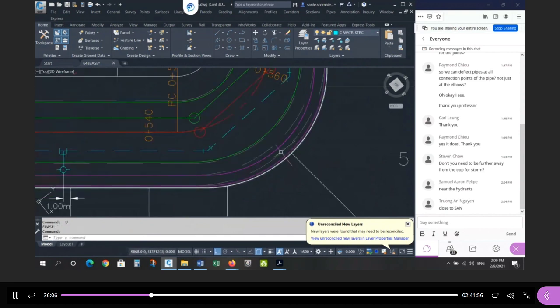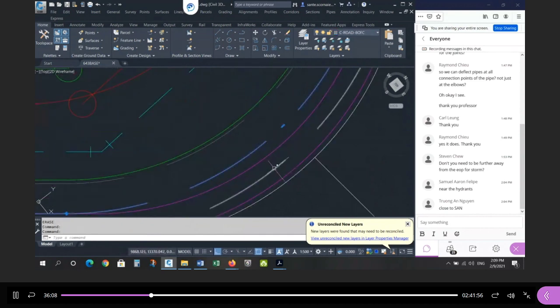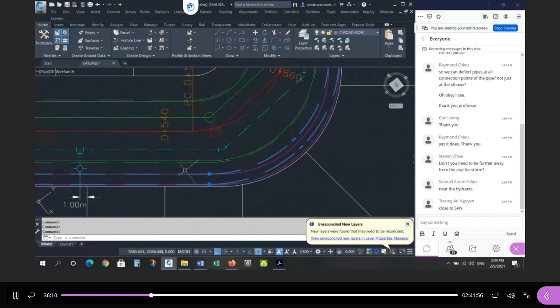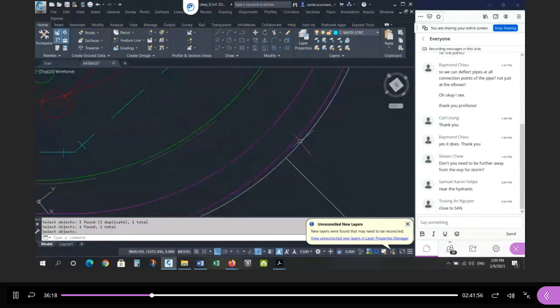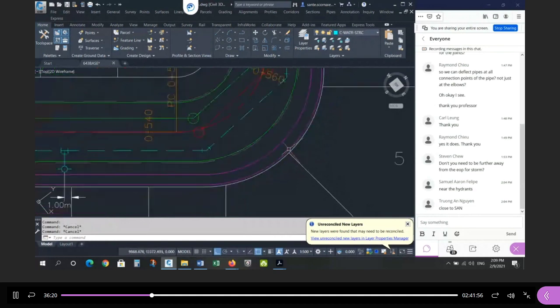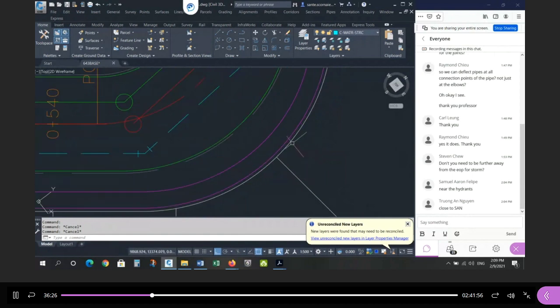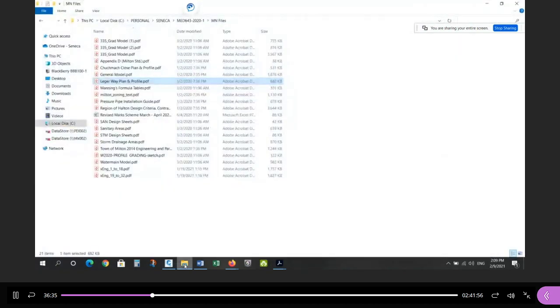Either way, either solution, you could put the sidewalk here and have a constant boulevard width, right? Back of curb to sidewalk will be constant around the curve. Or you can put the sidewalk here, which is always parallel to the street line, okay? Either one would work. It's in the boulevard, it really doesn't matter. What I drew, 0.3 meters off of this, is more in tune with the standard. What am I talking about? Let's go back to the standard, okay?